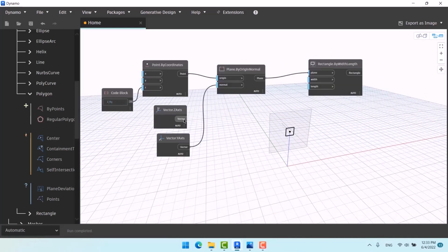So we learned so far how to use the default planes and how to define our planes in a specific location. But there's a hint here that you should pay attention to: all the planes that we have made so far are parallel to the global directions.